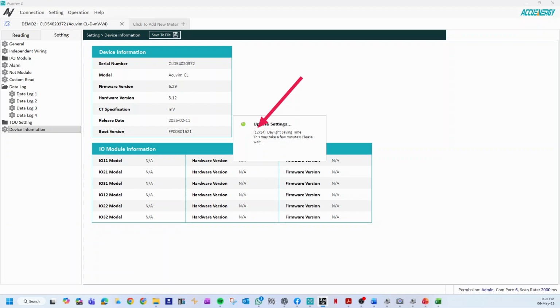Normally the data logging file is typical for the meters, but other settings like the CT ratio and the phasing in the voltage are normally different in the case of single phase loads using the meter as multi-channel. Now it's at 14/14. It's almost done. Now it's completed.